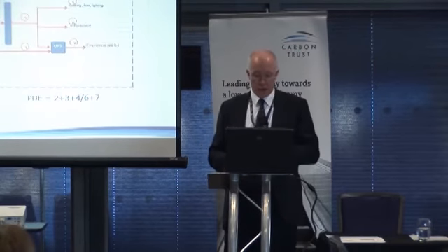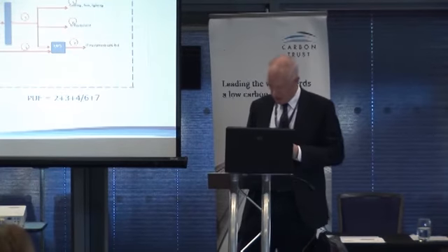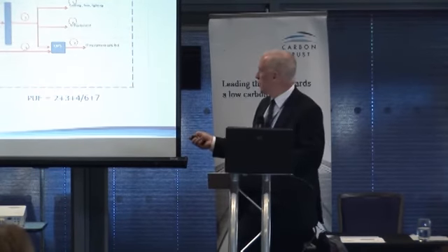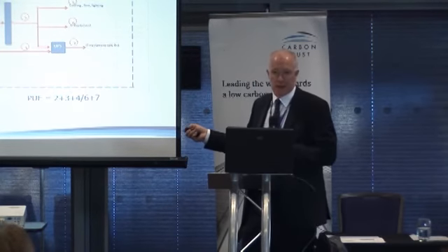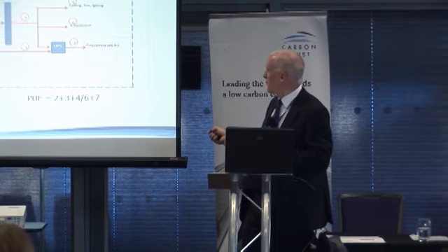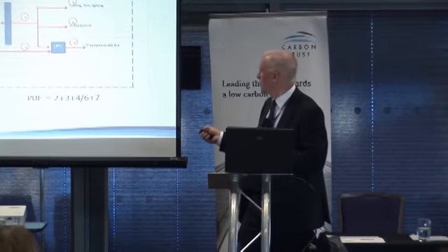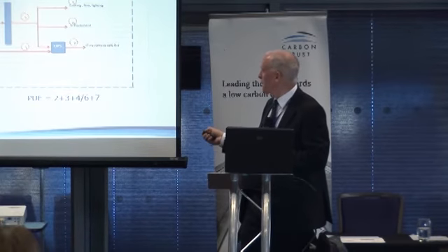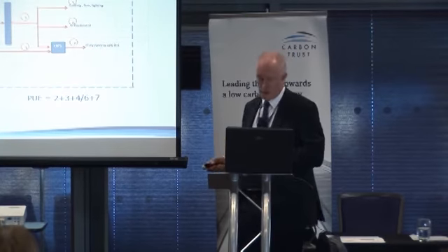This demands some monitoring, and here's an example of some metering that's gone in on a data center. Monitoring the main incomer. It might also do other parts of the building, so not necessarily that relevant. But then you've got your IT equipment here, which is your main supply. You may have IT equipment fed via your UPS as well, so essential and less essential there. And you're monitoring that total IT load, and comparing that against the total power, which includes the cooling that may be on the roof, and the power that is coming into your data center. And so your PUE is the total divided by the specific power that's going to your IT kit.